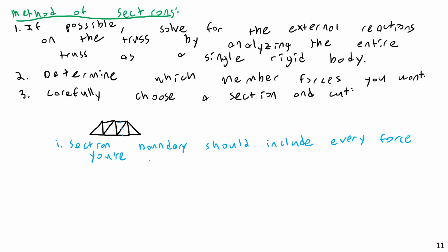Now, if I ask you for every single member force in a truss, if I ask you to find all the forces in all the members, then you're not going to be able to do that with a single cut. If I told you to do that using the method of sections, you would have to analyze that step by step and work through many different sections.